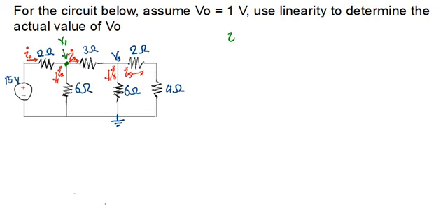We need it. So the question is, how do we come up with the V1? Because you have understood that the most important variables we need are the I1 and the V1. So how do we come up with those? First of all, we have to find most of these currents here, so that we will apply KCL, not KVL. We apply KCL here to find what I1 is. Since I have my I4 at this point and my I5 at that point, it's very easy for me to find my I4 and my I5, and the I4 and I5 will help me find my I3.